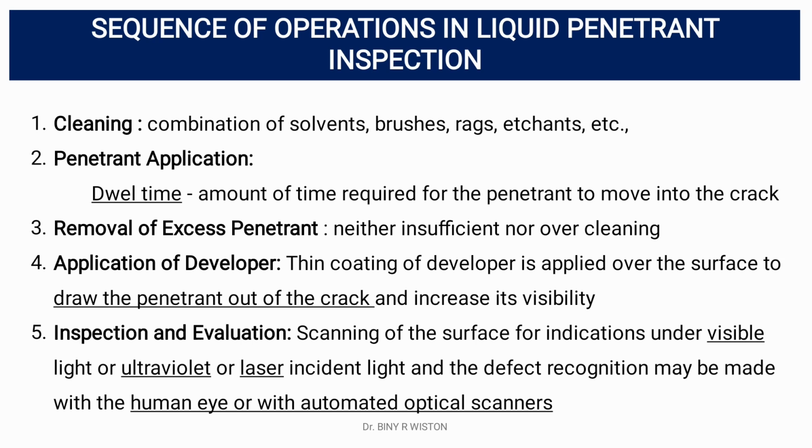So the sequence of operations in liquid penetrant testing includes cleaning, penetrant application, removal of excess penetrant, application of developer, followed by inspection and evaluation. Dwell time is the amount of time required for a penetrant to move into the crack.